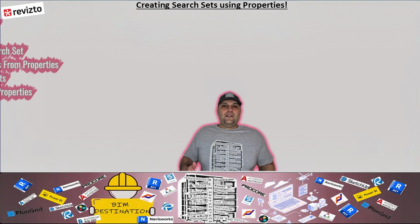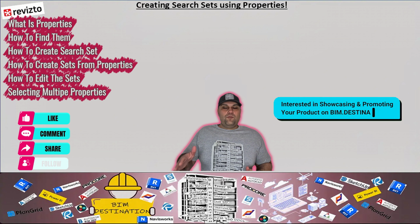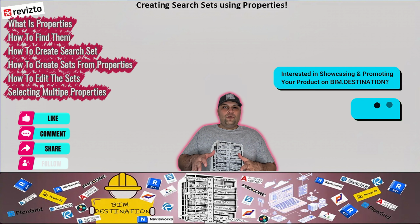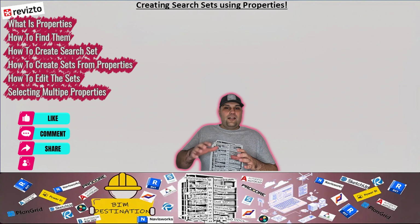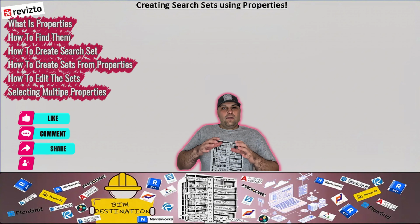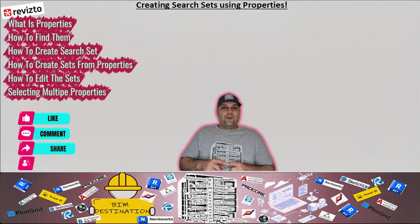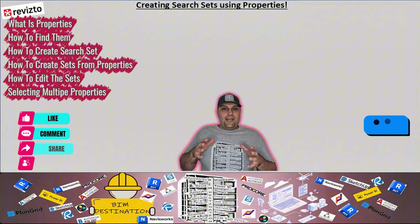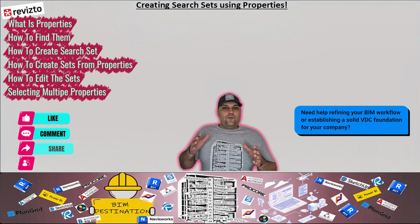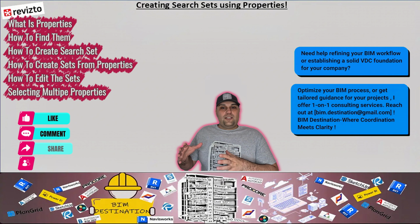In today's episode, Learning Revit, we want to take a look at creating sets using properties. This is a great tool that you can isolate a model, select the specific element that you want, and then you can create a set. The good thing about Revizto is when we bring everything through the Revit model, we have all the properties for that element. So when you select, you can basically create a set based off the property of an element. This is going to be very helpful if you want to get into details on creating sets and create your clash detection process.